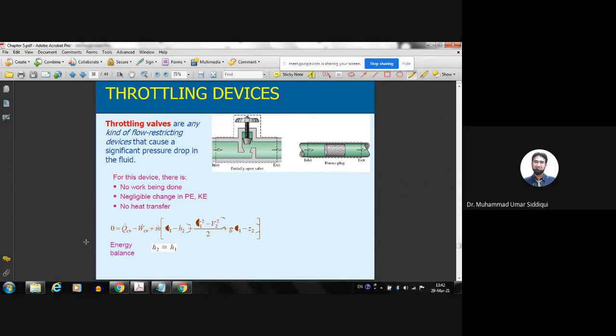And when you have a significant back pressure and you have a huge restriction for the flow, then a small opening causes a significant dispersal of water into the air. That dispersion of water is a specific phenomenon. We call it throttling. Okay, and how does this throttling work? What happens inside of throttling? Since we are restricting the flow and making the flow pass through a very small opening, overall enthalpy remains the same in this case. Because for the enthalpy to change, we need some space. So if the space is very limited, then the enthalpy change is not going to be there. So enthalpy at the inlet will be the same as the enthalpy at the exit. This is the fundamental thing in the case of the throttling device.